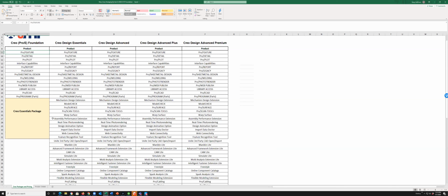Even though it says advanced assembly, or uses the word assembly, one of the big things it doesn't do is what's called copy geometry, where if you're building a fixture to hold a part, you cannot take that geometry and pass it to what you're creating. So there are a couple big deals that this doesn't do, like zones, and simple things like shrink wrap and some other assembly capabilities.